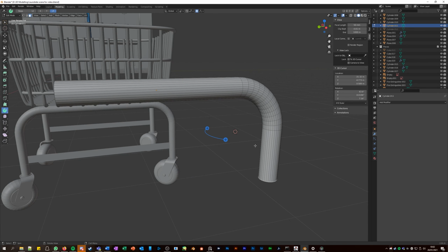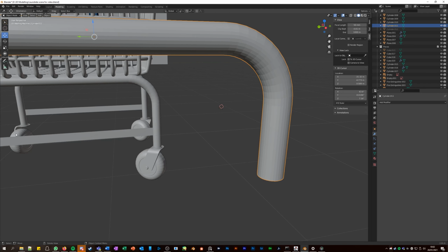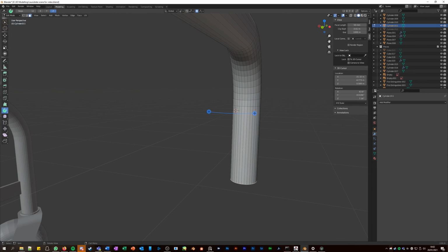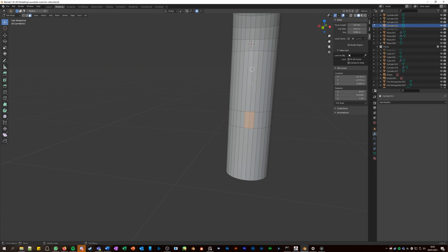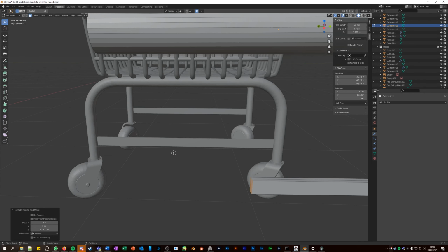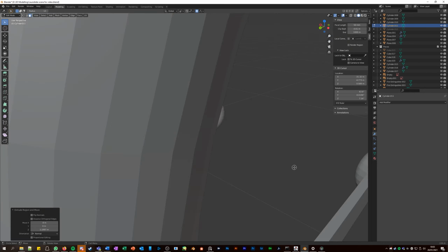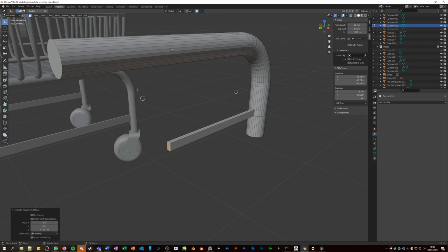I think I actually extruded both sides. Then to join them up using this beam, I took a loop cut here, a loop cut there. Took these two faces because there's a line down the center. It's centered at a line, not one face. So took these faces and just extruded them out this way. That's how I created this beam across the side. A bit thinner as there are fewer faces on this. There are more faces on this one than this one.